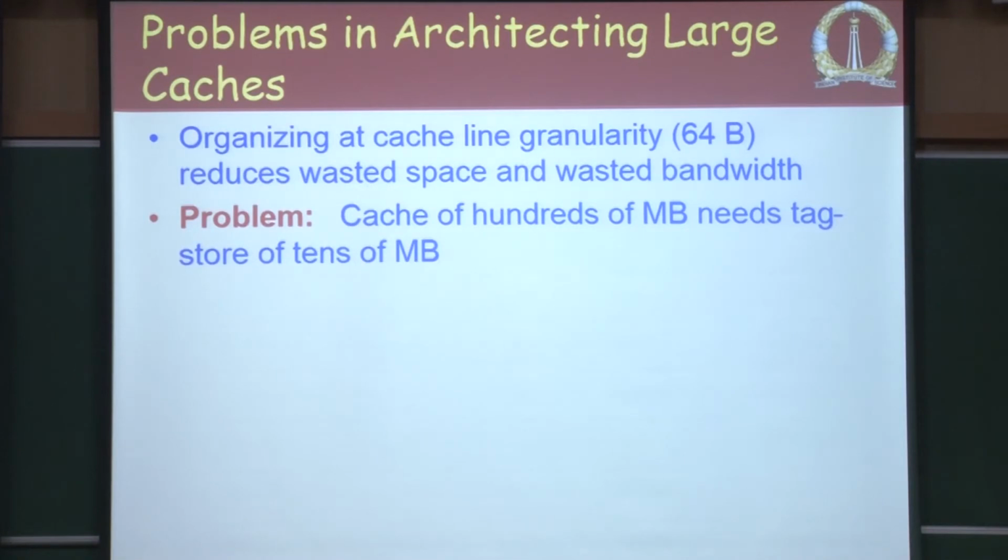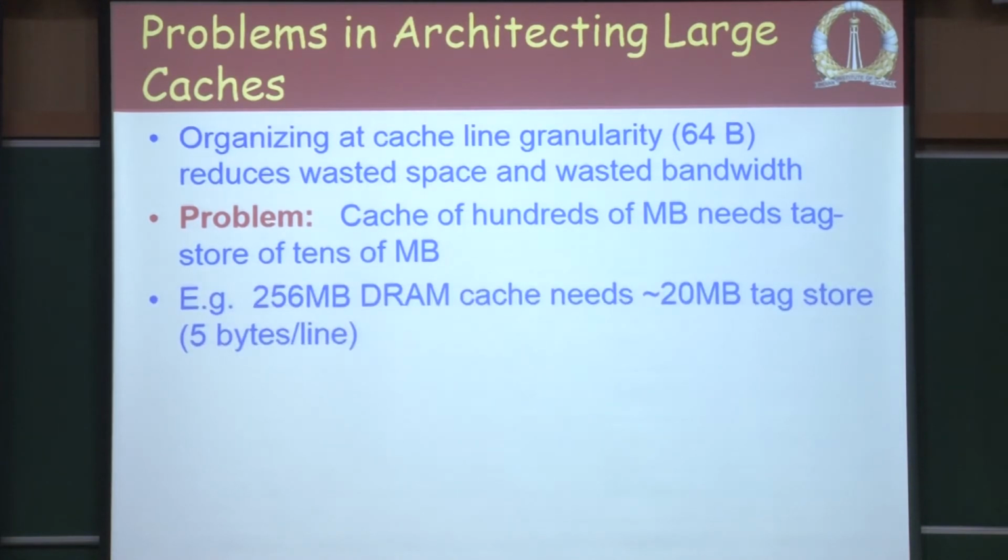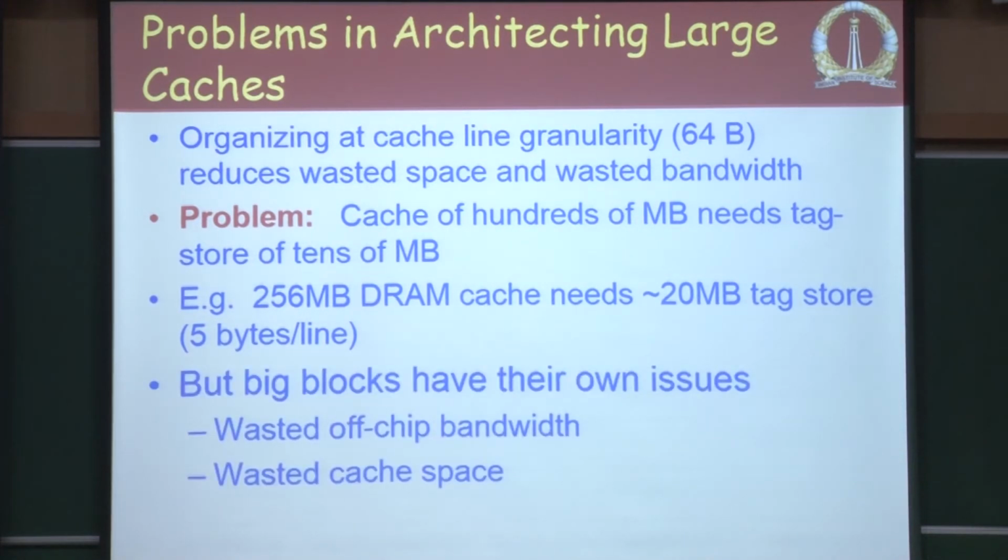Now, if you say that I want to have this metadata for my next level cache, the probable question to answer would be: would you be better off doubling your SRAM cache size rather than having this stacked DRAM cache? So, there are issues and challenges in actually having this much SRAM structure, and therefore, this is a specific example for a particular case.